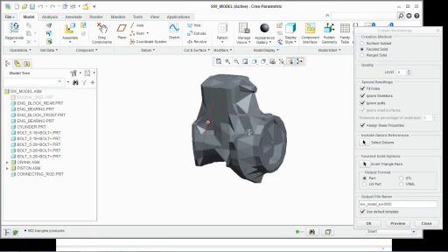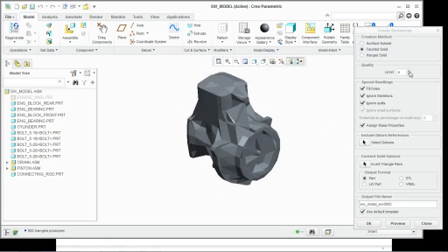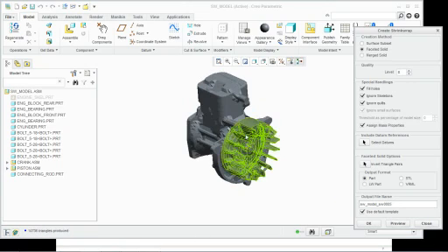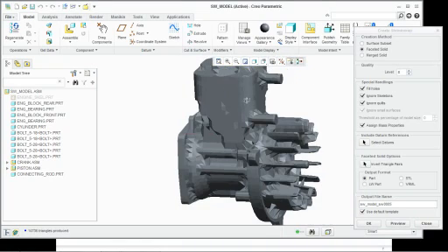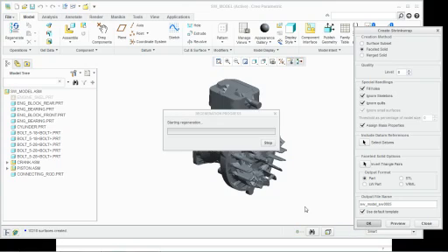Notice that's not really very good looking. That's pretty horrendous actually. So let's crank up the level to maybe 8 again. Notice 982 triangles produced. Click Preview again, and you notice now that's a little more like the shape we want. It still looks pretty hairy, but that's probably something that we're going to use just for showing a placeholder. The engine is going to be roughly about here. So we're going to click OK